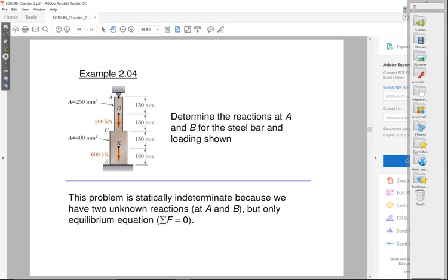So I have to look at the effect of those reaction forces as well. And those are the only two things that are going on. I have applied forces and I've got reaction forces. So I need to separate out what effect those two categories of forces have. And the way I do that is to separate this out into two different statically determinate problems.